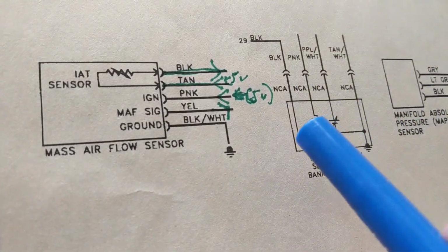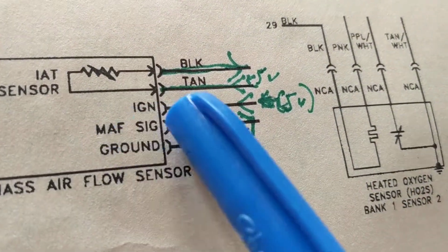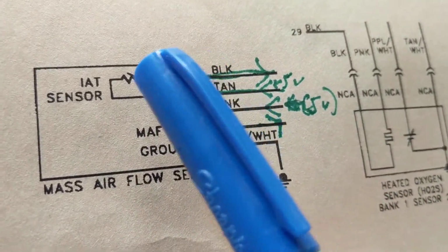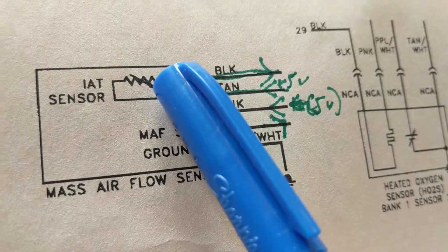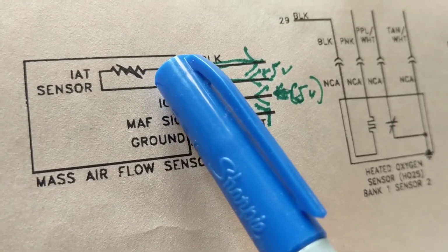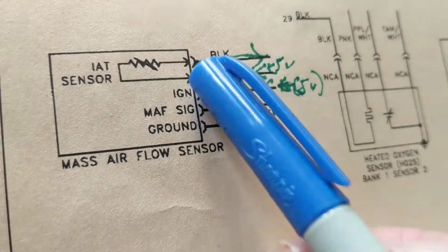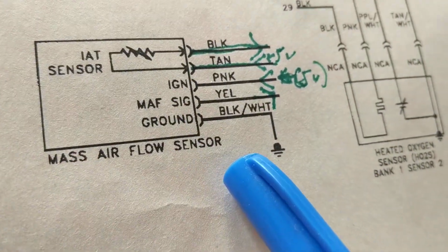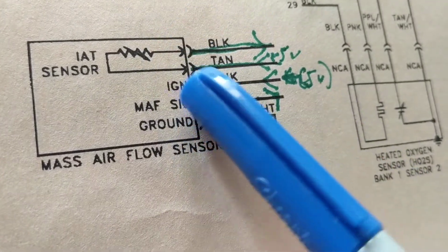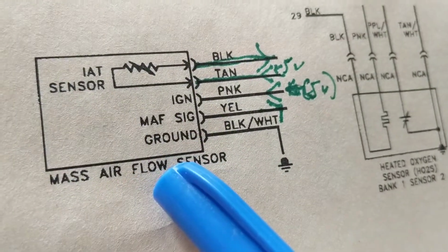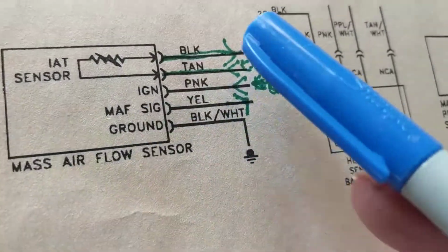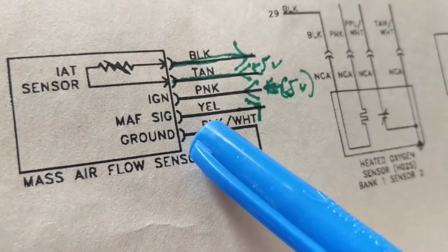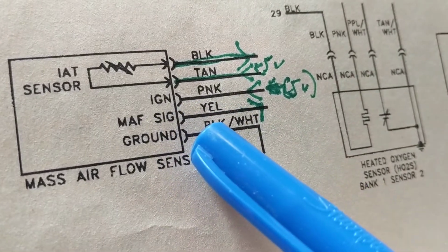Some vehicles have a mass airflow sensor by itself. Some have something called intake air temperature, which monitors the temperature of the air. Is it cold? Is it hot? In one unit. So therefore, you see this diagram? One sensor and another sensor are contained in one unit, like the Fords and all that. If you see 5 wires, that means it has 2 sensors in it. If you see 3 wires, that means it has a mass airflow sensor in it.